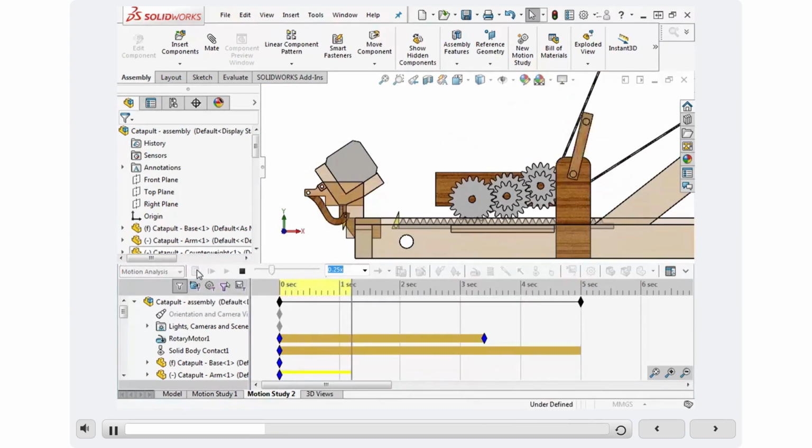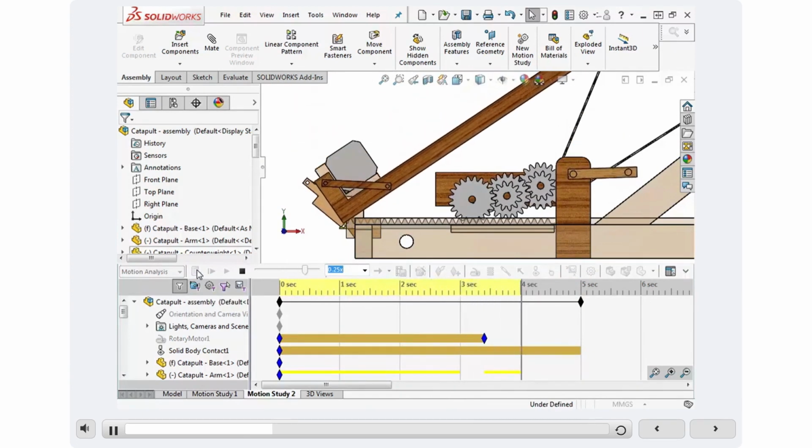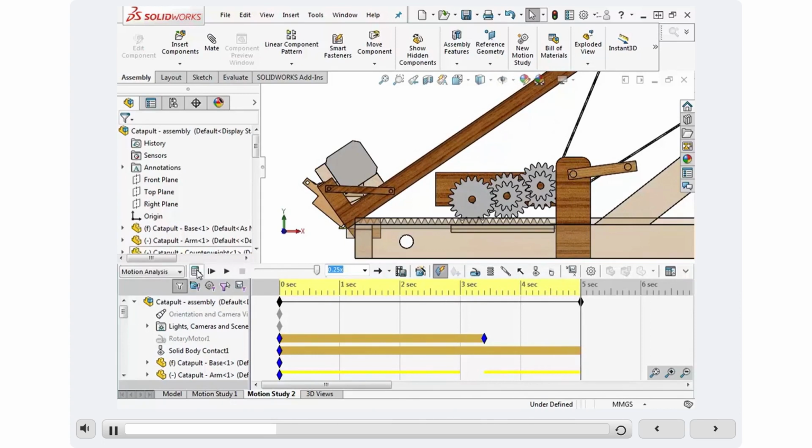When the simulation runs, the trigger on the rack mechanism will now contact the trigger on the projectile holder door and lower it. The following additional contact pairs have to be defined. Projectile to projectile holder door. Projectile holder to projectile. Projectile holder pusher to projectile. Using the procedure outlined in the previous steps, 3 separate definitions would have to be created. In order to save time, we will define contact between these components using contact groups.